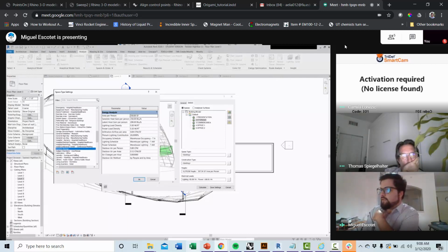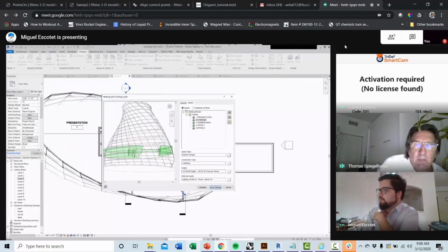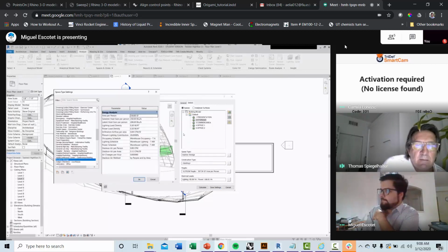Inactive storage, here it is. So you see it's already updated different elements. And Miguel, can you go back to that building type and schedule? Here we see a much more detailed space type setting for each occupancy type that is referenced to the International Building Code. So that's what we meant before when we did the conceptual energy settings, which is much more, as the word says, conceptual. Now here, finally, we can really go into the details and be very specific.